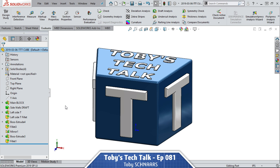Hopefully you answered that Control B is typically going to be faster, but Control Q is going to be a more thorough rebuild. And for me personally, I just always use Control Q. I pretty much use Control Q for everything until the rebuild starts to get exorbitant, starts to take too much time, then I'll switch over.